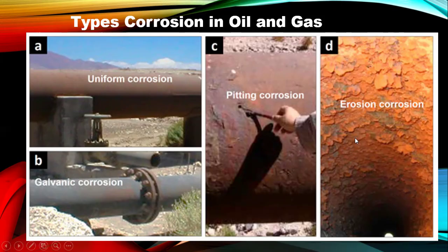We have other forms. We have other ones like the crevice corrosion. Crevice is when two metals are lapping together like this. The area of the lap is where that corrosion starts occurring, due to the fact that oxygen and other forms of this will just go there, settle down, and then they start propagating to form your corrosion. We also have other ones, like when you insulate a pipe, inside the insulation too, corrosion occurs. So corrosion inside insulation is also one of them.